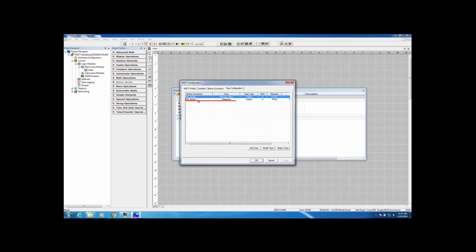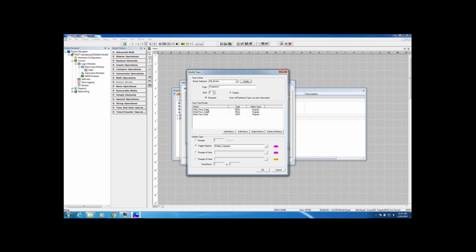I've also got another topic here called setpoints. The setpoints topic contains 3 variables. Setpoints for my mold temperature, for my mold pressure, and for my mold time. This is data, although it is published, I'm fully expecting to come back to me from this data package or whoever connects to me on the other end of the broker. In this topic, I'm only going to publish information on a trigger, so that if locally, let's say, a set point is made in the plant, that change can then be pushed to the broker and then it will be seen by the data package on the other side.